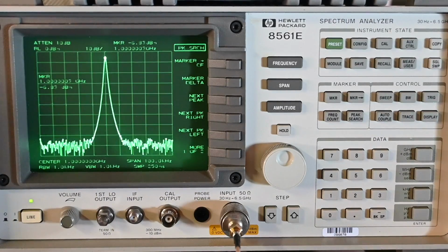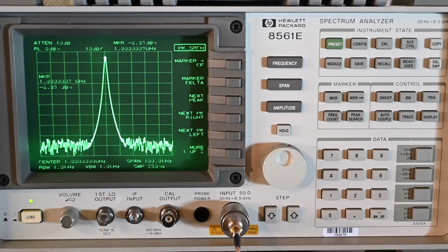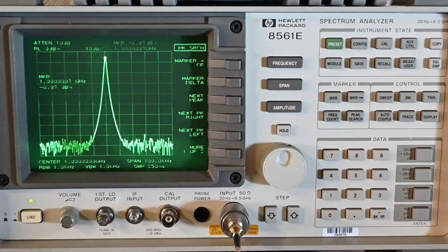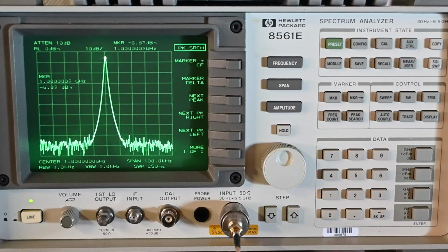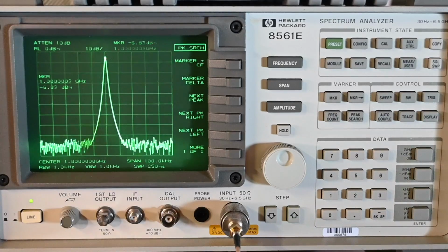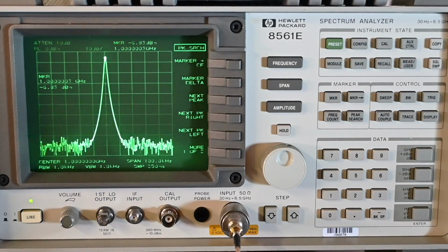Okay, so that's interesting, and that actually tells us maybe somewhere where the problem might be. Now, this particular spectrum analyzer has 2 bands internally. One band goes from 30 hertz to about 2.9 gigahertz, and then the second band, they call that band 0, but then band 1 is 2.75 gigahertz to 6.5 gigahertz. Now, if there's a drastic change when the instrument switches between bands, that can indicate a problem in a specific area or part of the RF path within the instrument. But that actually doesn't happen. So as you can see, we haven't really crossed over from band 0 to band 1 yet, but it is